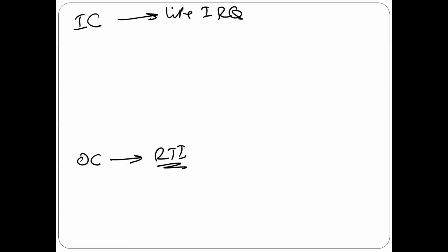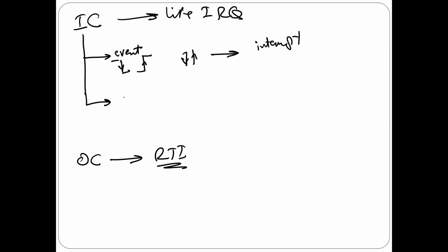Look here. What is input capture? Input capture means two things. Number one, every time there is an event, and the event in this case can be falling, rising, or both, and you can program it, every time there is an event, an interrupt is triggered. Number two, the count is stored in TC. This is what input capture is doing: every time there is an event, there is an interrupt, plus the current count is stored in a register. That's it. What is IRQ?